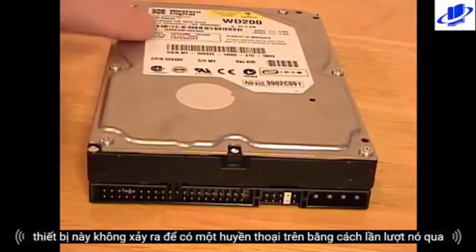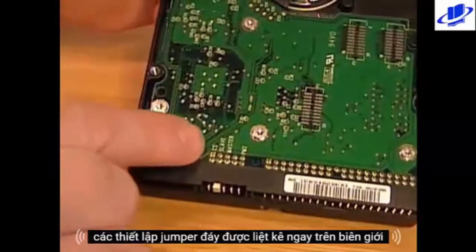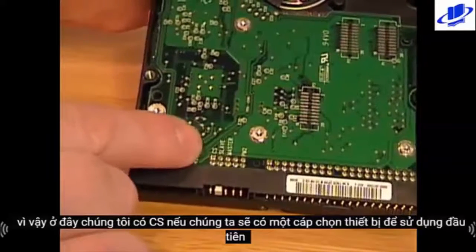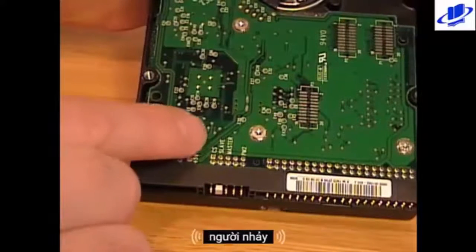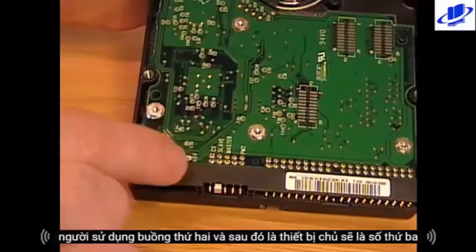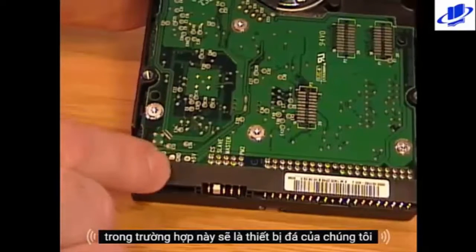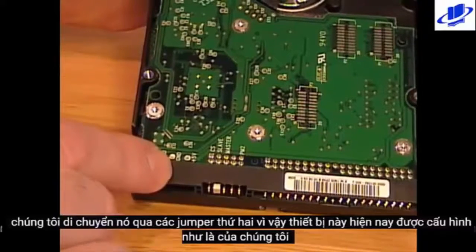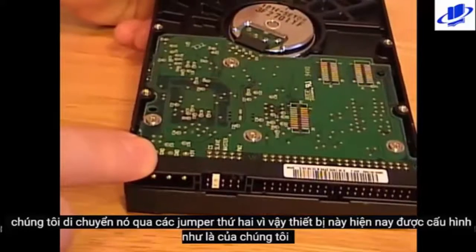This device doesn't happen to have a legend on top, but if I turn it over, the bottom jumper settings are listed right on the board. So here we have CS. If we were going to have a cable select device, we would use the first jumper. If we were going to specify this as a slave device, we would use the second jumper, and then the master device would be the third jumper. In this case, this is going to be our slave device. We will move it over to the second jumper. So this device is now configured as our slave device.